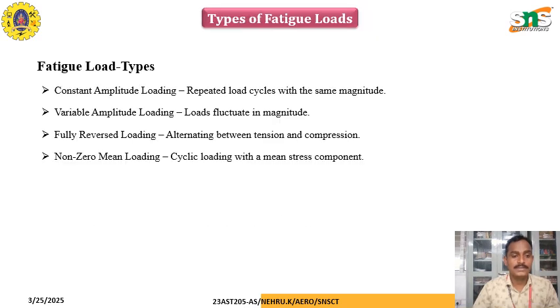Types of fatigue loading. One is constant amplitude loading, where the load cycles repeat with the same magnitude. Second, variable amplitude loading, where the load fluctuates in magnitude. Third, fully reversed loading, alternating between tension and compression. Then non-zero mean loading, which is cyclic loading with a mean stress component.